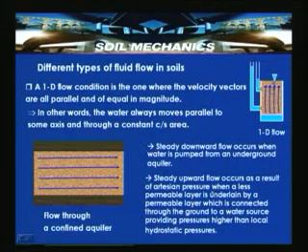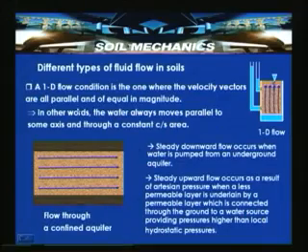We have also discussed the different aquifer conditions which are possible. So, the flow can be 1-dimensional. In this slide, we have seen a 1-dimensional flow which can occur due to flow from point 1 to point 2 because of the head loss occurring over that particular zone. In other words, we can say that the water always moves parallel to some axis through a constant cross section area. So, this is an example of 1-dimensional flow.